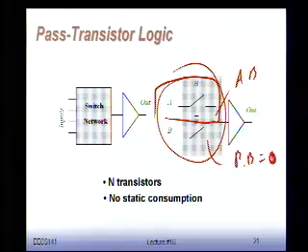So what we're going to do is build complex logic networks using only switches. Occasionally, I'm going to put an inverter in between, a buffer. Because if I have only switches, you never connect to VDD and ground. There's logic, logic, logic, logic, logic. You never connect to VDD and ground. If you don't connect to VDD and ground, what I get is something that's not regenerative. There's no way I can get gain. If I have a sequence of switches and I inject noise on one side, noise will happily propagate and keep on adding. So switches themselves are not regenerative.